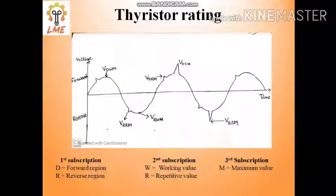Okay, and in case of VDRM, now look here: D stands for forward region, R stands for repetitive value, and M stands for maximum value. Okay, so VDRM is known as the maximum repetitive forward working voltage.